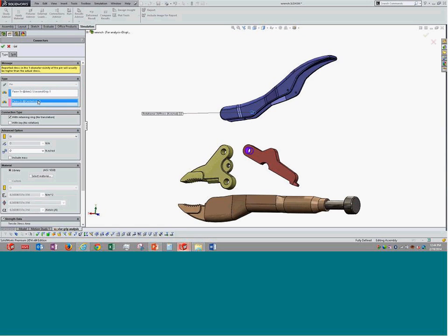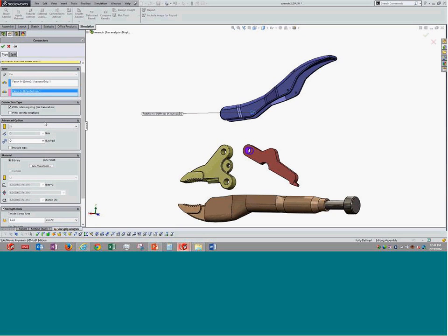So this is created. Pin has different things. One of it would be whether there is a retaining ring. So this is going to decide if there is going to be any axial movement of this ring, and whether you want to restrict any rotational movement. Again, that can be decided here.